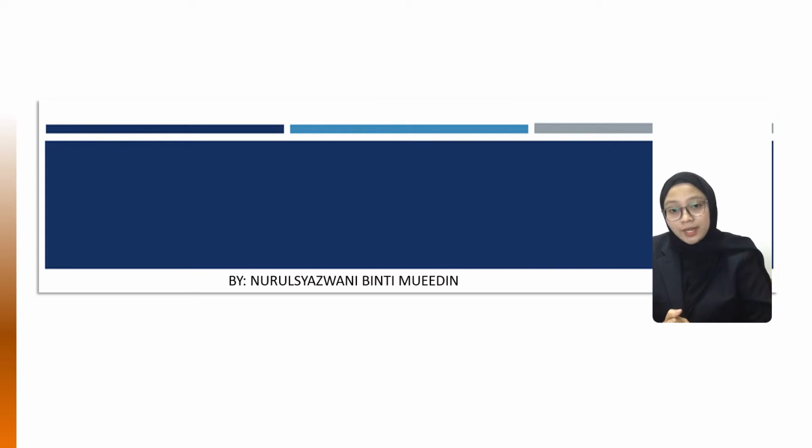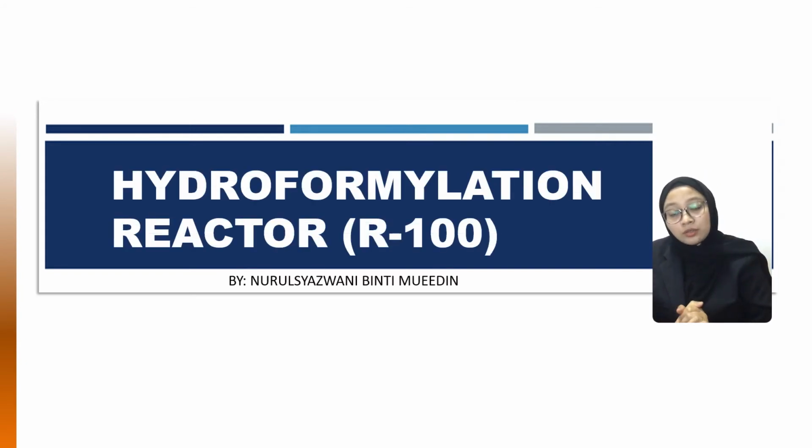We chose a fixed bed reactor in order for the hydroformylation to take place because our reaction involves a heterogeneous gas-solid phase reaction. In order to achieve higher conversion per weight of catalyst, we need to use a fixed bed reactor since the FBR has better conversion than other catalytic reactors. We use solid rhodium as our catalyst to speed up the rate of reaction because it has high reaction rate, high stability, and low production of byproduct. The flow is characterized as plug flow since there are tubes in the fixed bed reactor to place the catalyst.